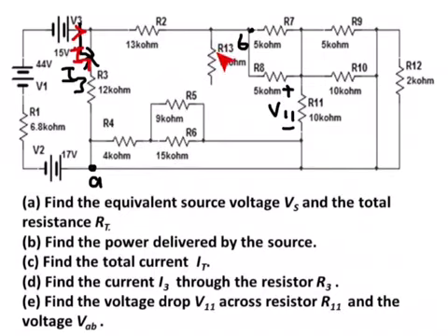This resistance R13, its other end is hanging in the air, so there can't be any current flowing here. So this resistance also is not part of my circuit. Let's take a look. We have here R9. It's obvious it's parallel with R10. But what may not be that clear is that this point is the same as this point, the same as this point, and the same as this point as well.